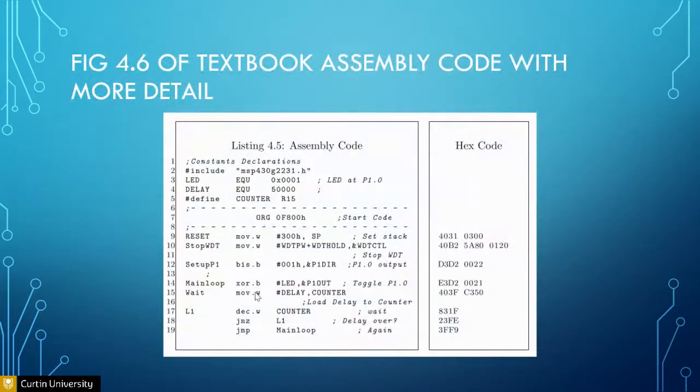Okay, this is an example of an add. Now in this example, you add a lot of labels. So that when you jump, for example, jump not zero means that if the zero flag is reset, it will jump back to this part of the code called L1. So these are basically labels. They enable the instructions to jump to certain parts. Why? Because in assembly code, we don't have a while loop or if else or whatever. We need to rely on labels to help us do programming.